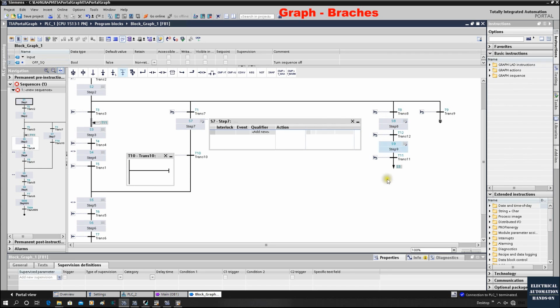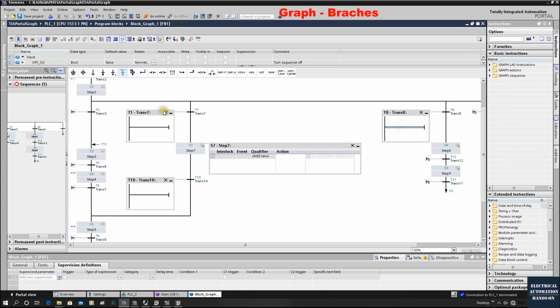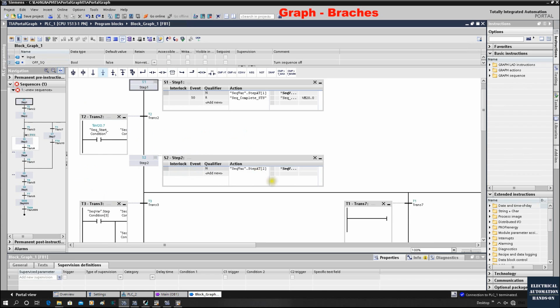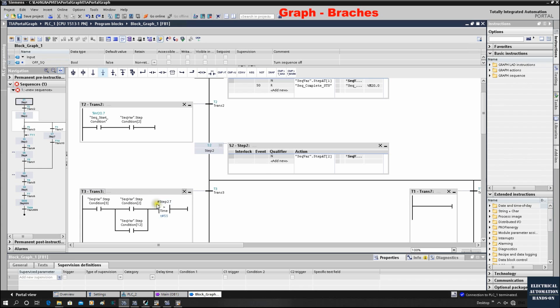Typically, each branch is one specific task, and the condition to run this branch could be here, right? You can either run 2 branches together, or most cases will run 1 branch at one time, right? So you need to carefully manage your conditions. But once it jumps to these branches, it will be very clear, because once it jumps to here, it will be highlighted. You can very clearly see what is running. And in the meantime, you can expand or close. Expand, then it can open everywhere, and you can open these step conditions.